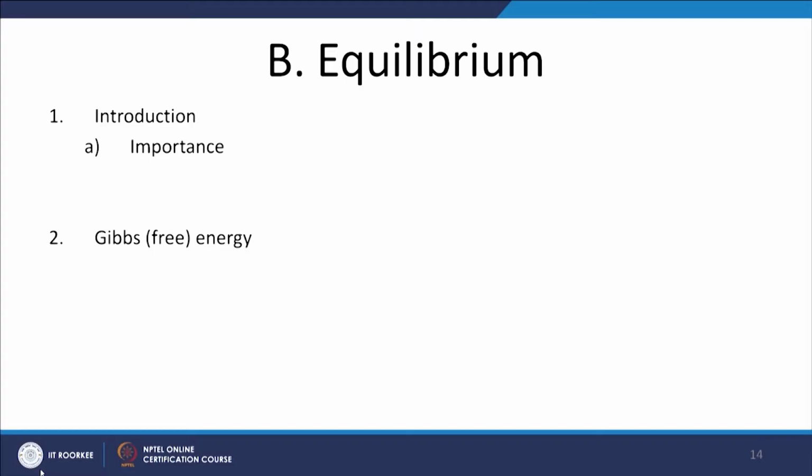So I believe we already looked at some examples relevant to the importance of equilibrium. One example we looked at in the previous session was trying to identify the maximum heavy metal removal at a certain pH, let's say. Heavy metals can be precipitated out, and given the relevant pH and the ligand concentration, you can estimate to a great degree of accuracy the greatest possible removal, or the highest percentage removal of the relevant heavy metal or mixture of heavy metals. That's one particular example, but equilibrium is applicable to any engineered or natural system.